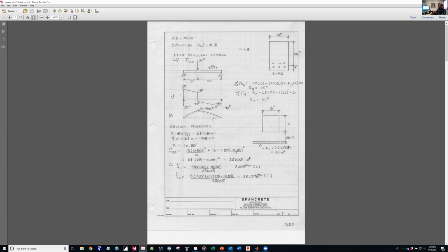But when we're talking about deflections, if we're talking about the load it takes to cause cracking, or checking a crack width, or checking these service stresses, f sub c and f sub s, well, these are all based on the flexural equation. That stress is equal to My over I. My over I is only applicable in the elastic range of a material.